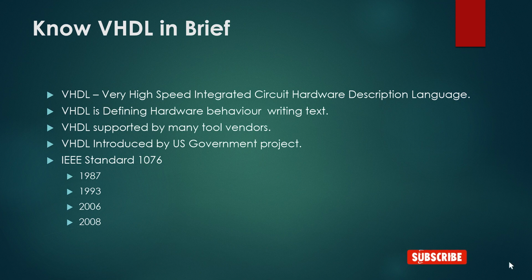But let me tell you this: VHDL is a design language that describes the behavior of what you want to get from your digital system, and the tools do the job of translating that description into the semantic logic and FPGA mapping. And let me tell you one more thing: VHDL not only allows sequential statement execution, but it also allows parallel execution of statements as well, which we will learn later.